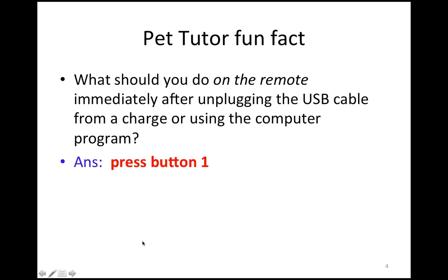The reason you do that is when the remote is plugged into the charger or plugged into the computer, it disables the sleep timer that's internal to the remote, and that saves the battery. So when you unplug it, if you don't re-enable that sleep timer, the remote will stay on. And we've had people say, oh, my remote's not staying charged. And I actually can't think of a single time where the problem wasn't they forgot to push button 1.